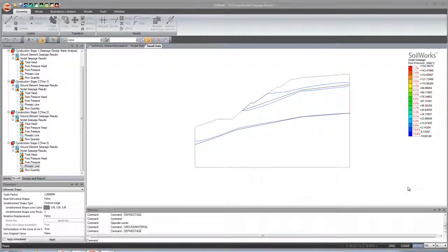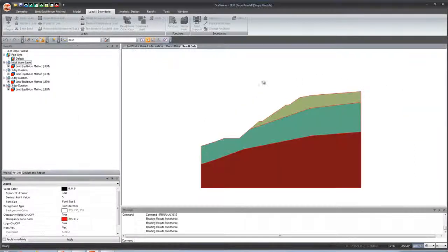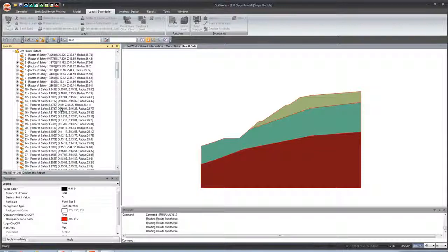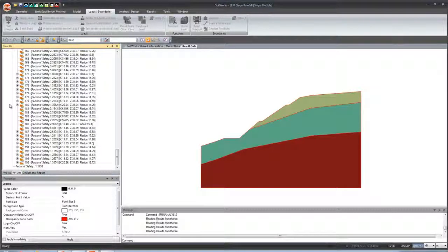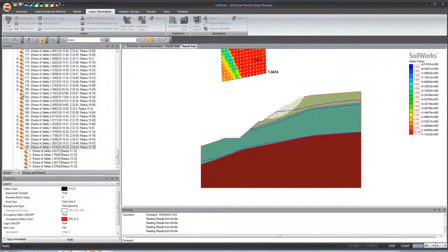So now we've obtained the seepage analysis. As the ground's becoming more saturated as more and more rainfall falls through the different days, so obviously we've got day 1, day 2, the factor of safety is decreasing. As you see by day 2, it's actually decreasing by a factor of 1, and then it goes down even further by day 3.